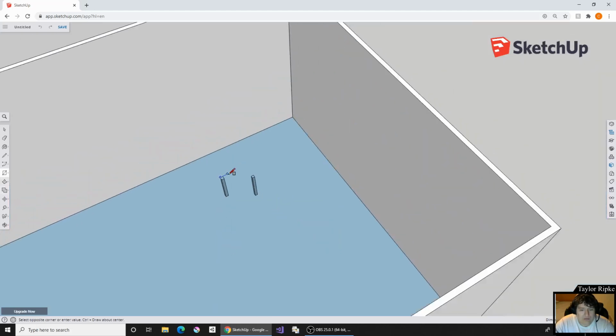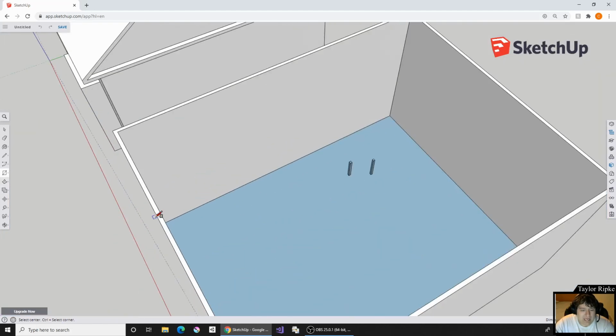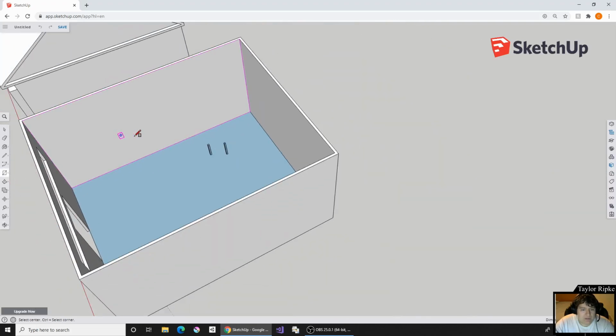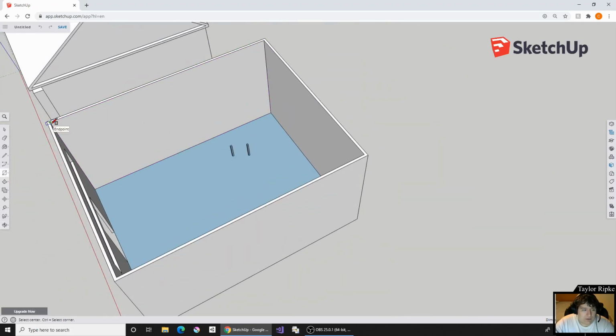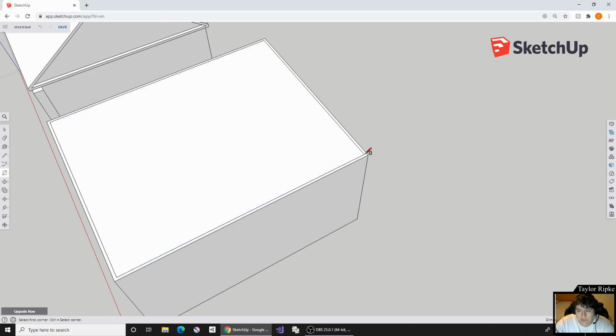But what I'd like to show is you can connect geometry per se. So for example, if we wanted to put a roof on this thing, we could start with our rectangle tool here, and what we're going to do is not have it along that axis. I'm going to go ahead and bring it this way and select it directly on that one. So I connected it from this corner to this corner. SketchUp, whenever it finds 3 points or more to connect, is going to build a face, because that's just the nature of the 3D geometry. When you have 3 or more points, we can go ahead and create a triangle or a rectangle, etc.